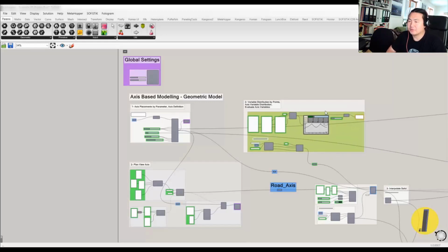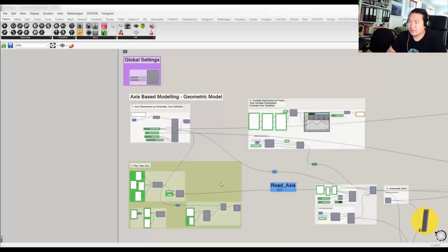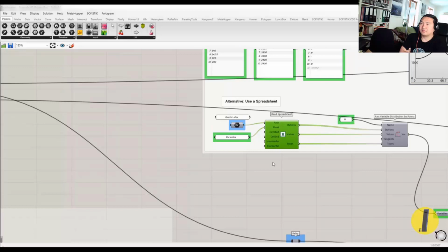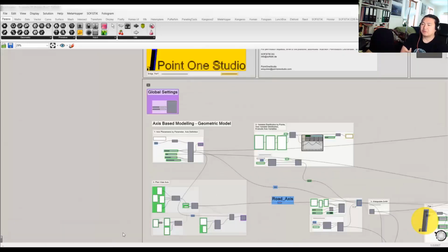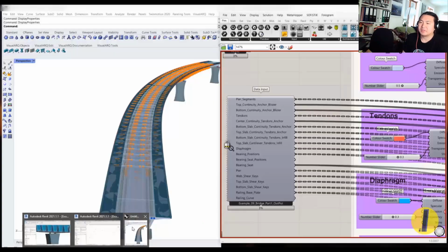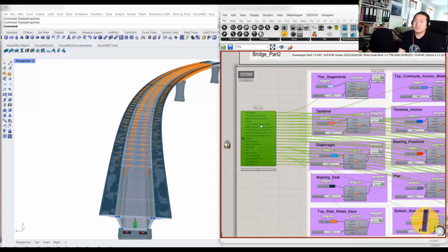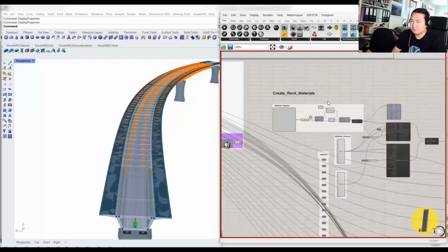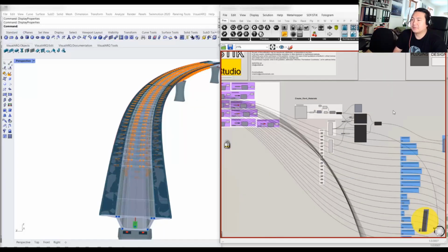It's very challenging to generate this geometry manually, but I understand many bridge engineers use 2D documentation tools such as AutoCAD and model in AutoCAD for one segment, and then just repeat pretty much the manual modeling process. Or some bridge engineers use specialized software like Sofistik for bridge engineering in Revit that helps them automate generating the bridge model.